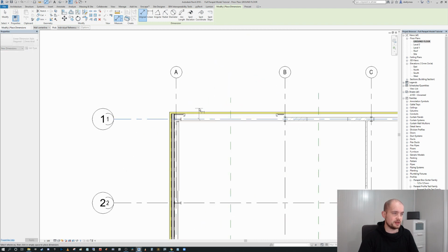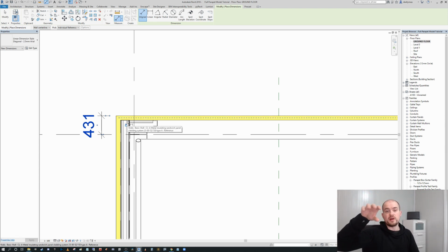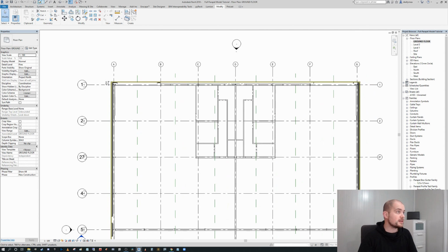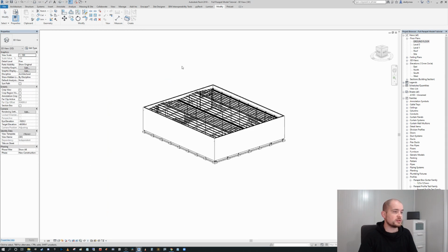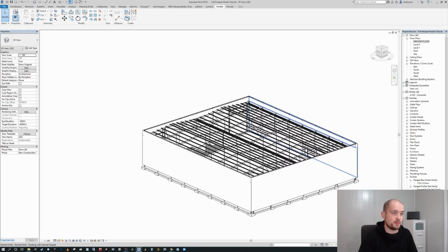And this is so, should we have a building set out change on the boundary and our grid setting out is updated, we don't need to go and take all the individual roof elements, the parapet wall, the parapet capping, the gutter, all of that, and manually change them. All we need to do is vary the grid, and everything should move with the association to the grid, okay? So that is part one, which was how to create the cladding wall inclusive of the internal parapet, okay?